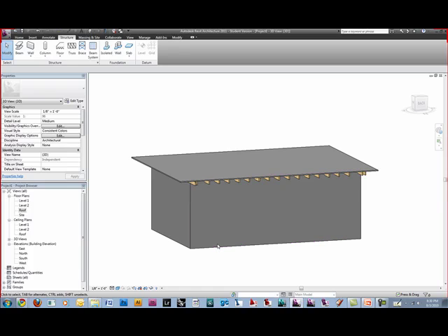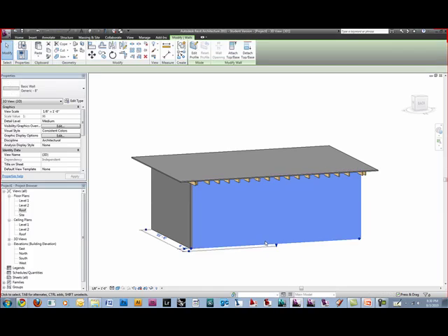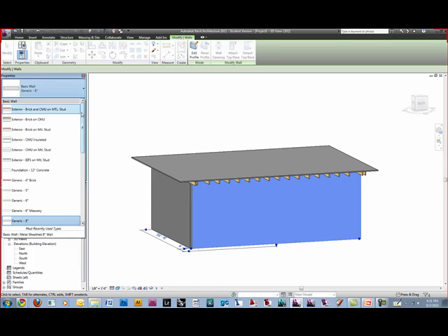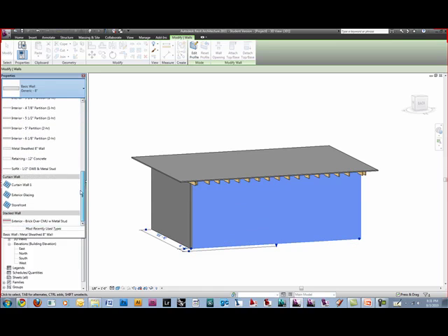What we're going to do first is place a generic wall into a curtain system. I'm going to take this wall here, which is just a generic wall, and change it from our generic 8-inch to just a plain sheet of glass, and that type is called Curtain Wall 1. This gives you the most freedom to do whatever you want.